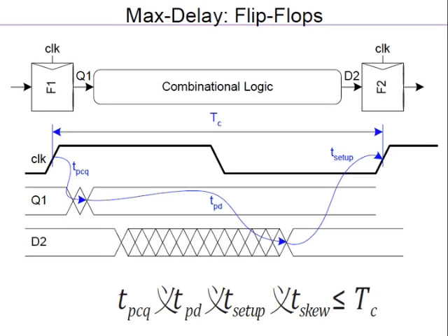So being able to automatically adjust the voltage where you are just meeting timing, with a small amount of margin, will be the most power efficient, energy efficient point to run. Okay, so that is what dynamic voltage scaling tries to do. It tries to hunt and adjust the voltage such that it will be at the most power efficient point.